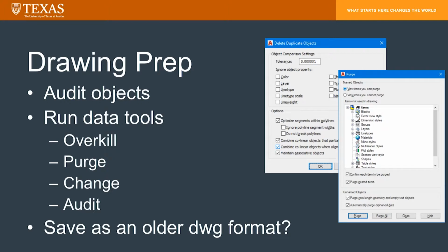Now, we use change, and I'll tell you why. So what we had found in our CAD drawing is that they tried to incorporate 3D drafting in their 2D environment. And so we found points that were at -1 million or +1 million. And while you can probably use flatten to do this, with change, you can change the elevation properties to 0.